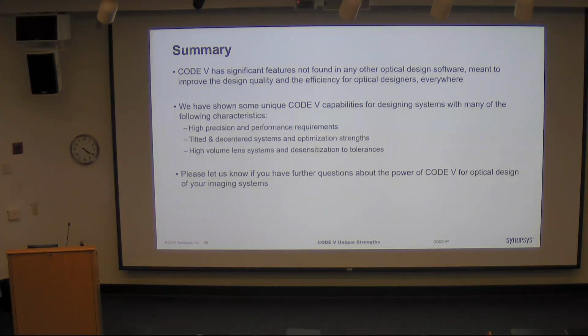Code 5 can very quickly tell you, okay, if you move those parameters by this much and this much, it is going to get your perturbed, misaligned exit pupil functions to match as closely as possible to the perfectly aligned. Sometimes it helps if you do it in multiple stages. You do one stage if you're pretty far out, you put in those adjustments, you do it again with new interferograms, and that will get you closer.